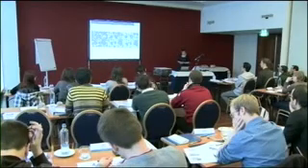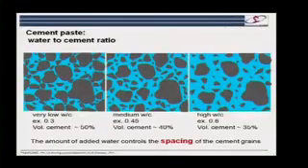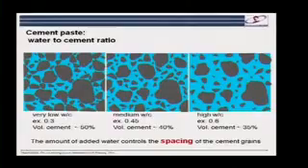Now, the other way you can think about it is that the amount of water is really controlling the spacing between the grains. And that's what I've tried to show in these diagrams here, that as we go to higher water-cement ratios, the cement grains become more widely spaced. This makes it easier for them to move at the beginning, easier to place the concrete, but it then means you've got more space that needs to be bridged by this new product that's going to form during the reaction,